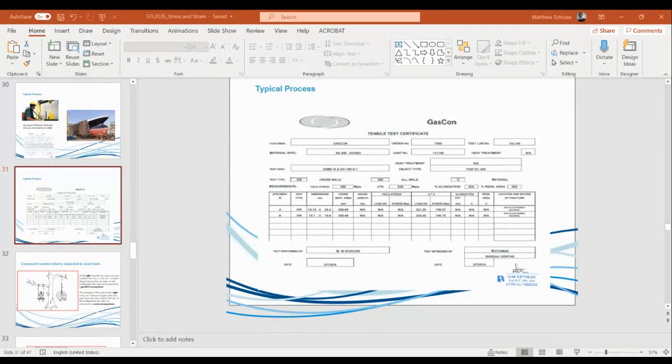They'll just reuse it. So sometimes be a little bit skeptical of them. Check the date in particular. That's the most important thing on there. When was that certificate stamped and signed? Otherwise, when you request it, they just send you some old one that they've got on file, and it becomes very hard to trust the material. For sure. That's why, in the case where I work, we have to re-verify. We had our own lab to make sure that it is exactly what it is before we proceed. Thank you for that. Exactly. Anything else?